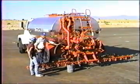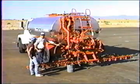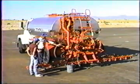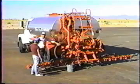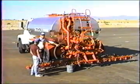You can pump water, you can pump diesel, you can pump paving grade asphalt, and none of those things will affect that seal. If this truck didn't have the low maintenance pump feature, then it would have a packed pump, and there would be a packing here that you would have to adjust periodically in order to keep the pump shaft from dripping.